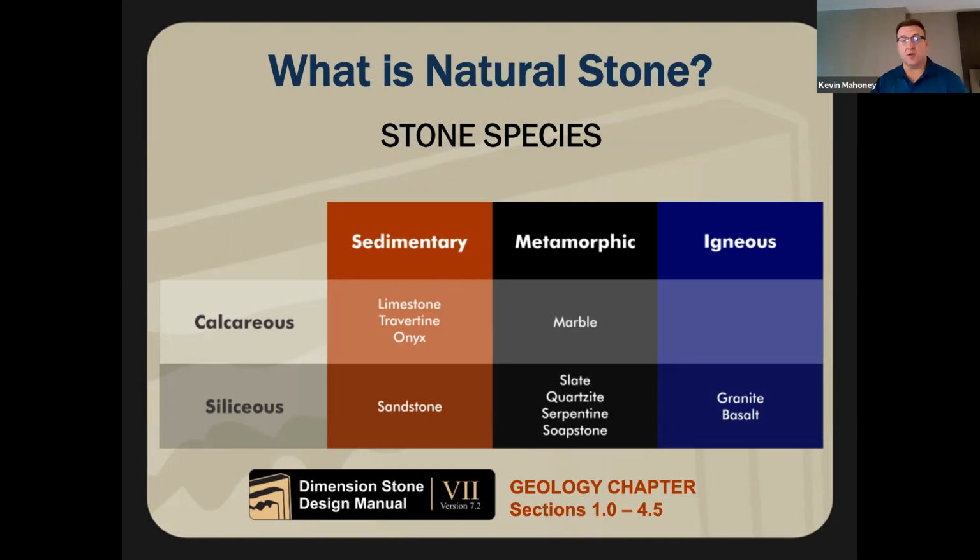Metamorphic, similar. Slate, quartzite, serpentine, and soapstone. We'll talk about those and some applications on those stones in a little bit. And then there is siliceous igneous, which is granite and basalt. Very dense, very durable, and usable rocks in a lot of situations.